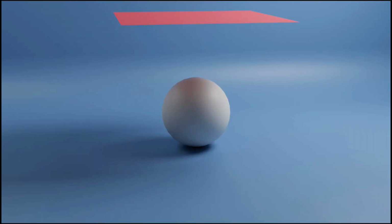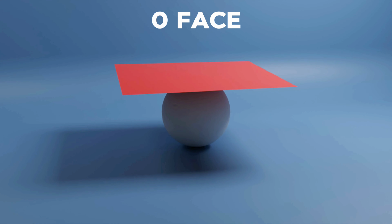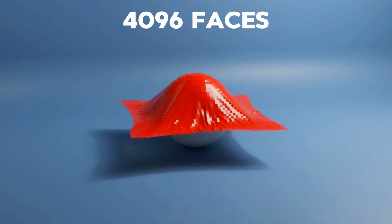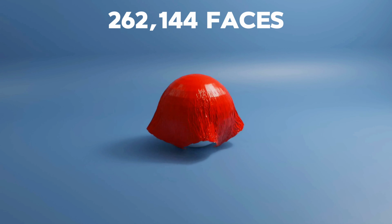your cloth. Adding and subdividing the plane. Blender's default plane only has 4 vertices, which isn't enough for realistic cloth deformations. When cloth interacts with other objects or folds on itself, these deformations are calculated based on the number of vertices. If you only have a few, the cloth will look blocky and unnatural. To fix this, you need to subdivide the plane.